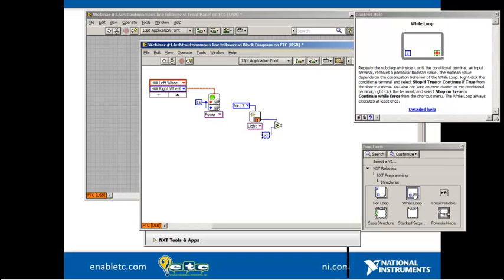And since everything is graphical here, it's a natural question for those of us who have experience with a text-based programming language. Well, how do we put a loop here? How do we wire it around? Well, the way that loops are done, the analogy within LabVIEW, is that loops actually encompass code. So if I click and I drag to create my while loop, and I'm carefully dragging to make sure it encloses all of the code that I've already created, we see here that we now have our functions inside our loop. And what that means is the stuff inside the loop is going to run over and over and over again.